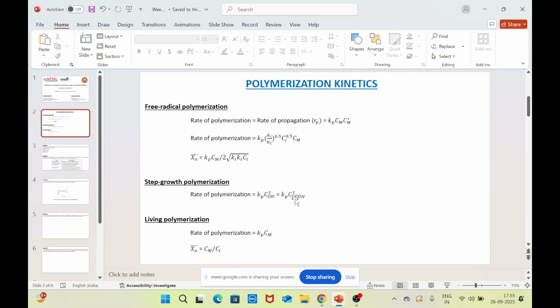So as these polymer pellets move, they are also going to be heated up by two means. One is an external source of heat supply, and another one is the friction, as well as the viscous heat that is going to get generated as they move forward through the rotational motion of the screw. Because of the heat that gets generated, the polymer pellets are going to form a polymer melt. So as they reach the end of the screw or move closer to the die, majority of the